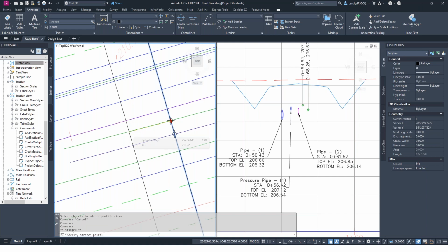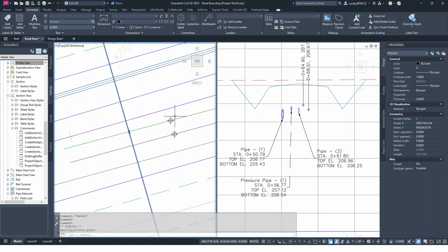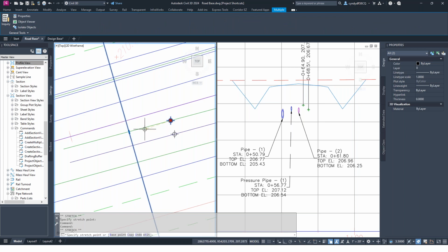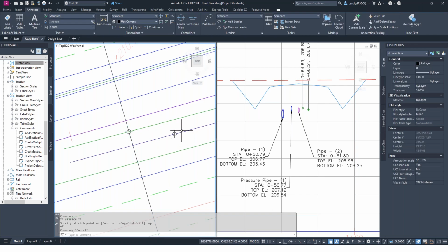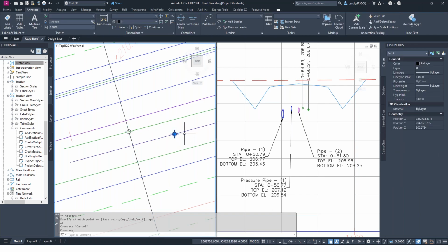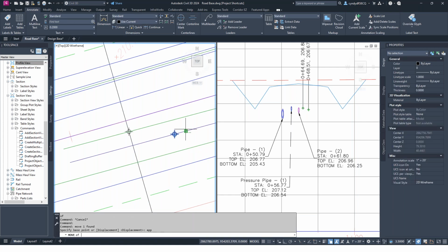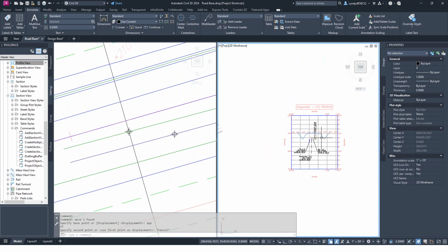Right there, move him up. Well, the points, of course, don't move with it, but I can just go ahead and take the points, do the same thing I did before with my apparent OSNAP, and move them to the next location. And they update. So take that, move the point to apparent OSNAP here. And so they're updated. The labels update and all of that.